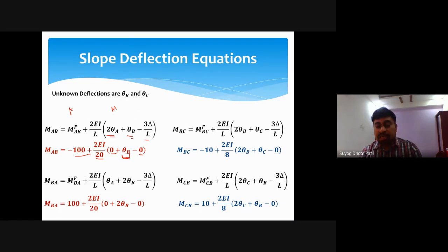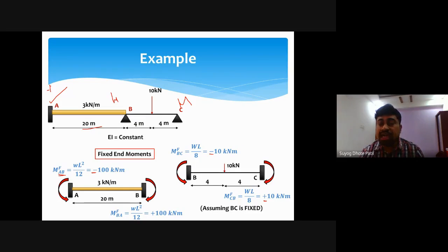And in the problem figure, at B it is a hinge joint. At a hinge joint, displacement in the vertical and horizontal direction is restricted, whereas rotation at B is possible. Practically, rotation is possible at joint B as well as at joint C, since both supports are hinged. But vertical and horizontal movement is not possible.